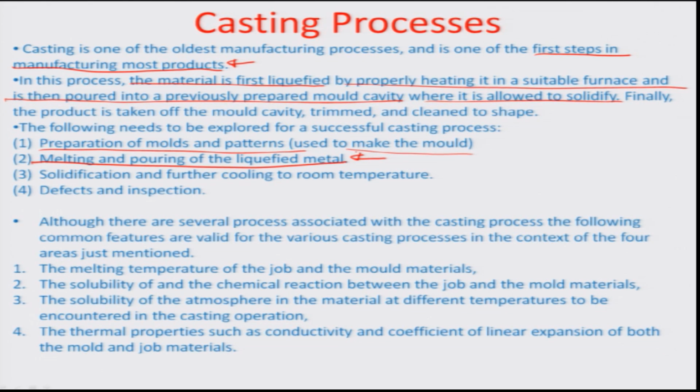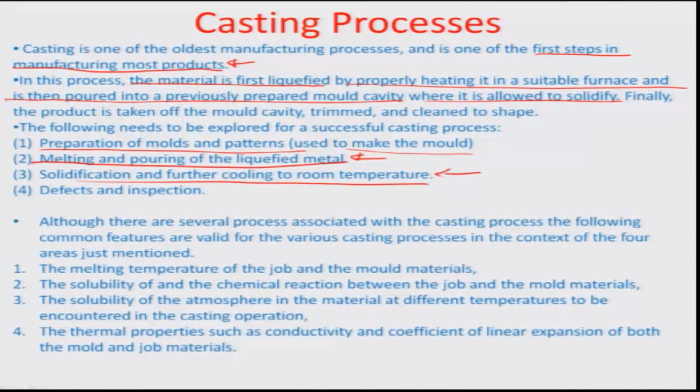During all this process, there is always heat transfer, because remember, the mold is always at a lower temperature than the super hot liquid metal which is flowing through it, and therefore there is always a possibility of solidification before entering. So the processes should be designed in a manner so that the liquid metal really enters before the solidification happens. And then you have to remove heat for the solidification and further cooling to room temperature.